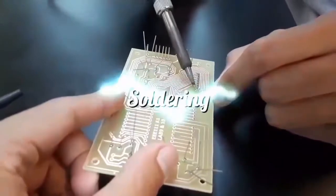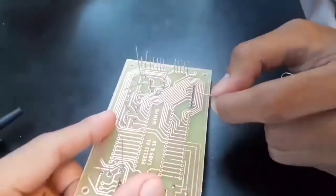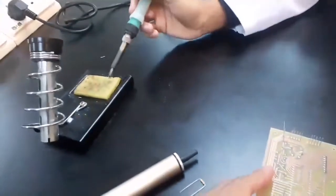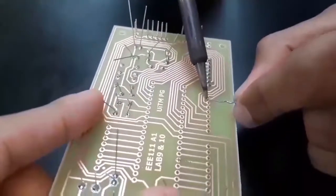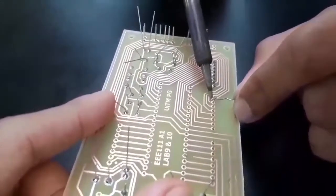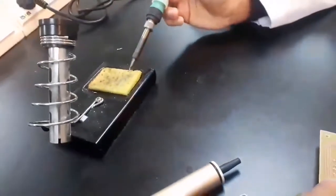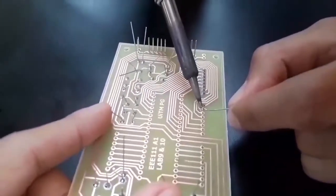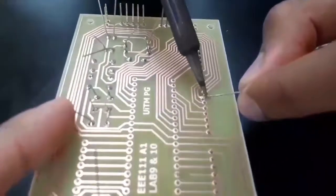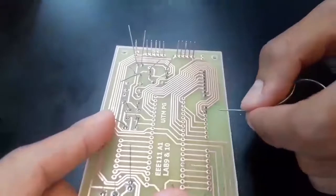For the soldering process, components are inserted and the leads split so they are held in place. Clean the solder iron tip on the sponge so the excess lead is removed. Then heat the copper on the board and apply the lead. This is done in order to heat both items at the same time. Solder iron is removed in order to allow the solder joint to cool naturally.